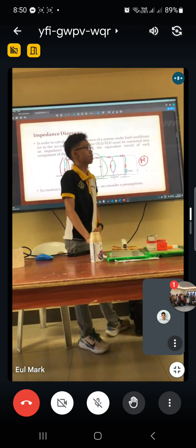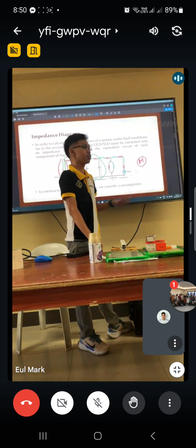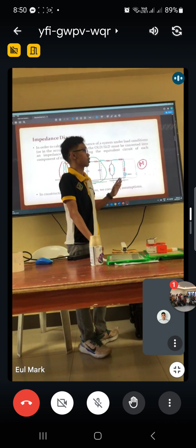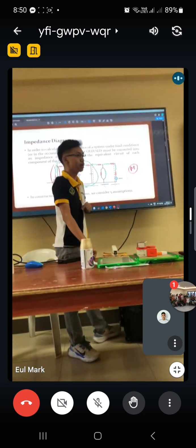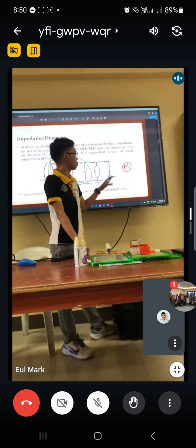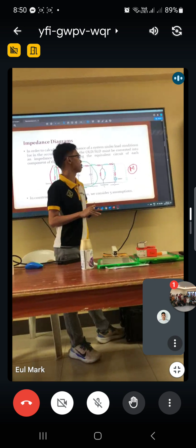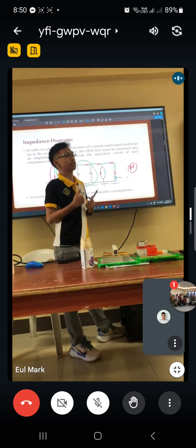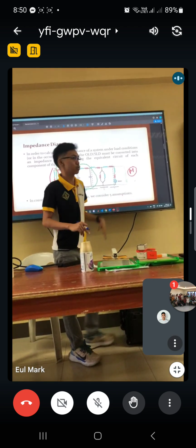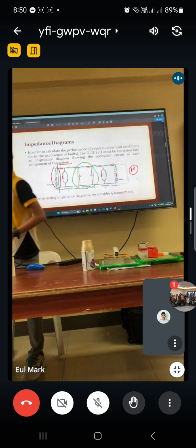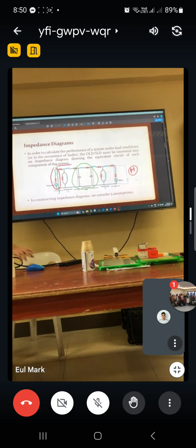Let's say you have a process load, usually motors. Static loads are those without rotating parts. A motor's load depends on what it drives. If you have a heavy load on your motor, the torque is higher, and so is the power. That's why your motor load fluctuates. A static load is constant, let's say 40 plus j60 MVA. So that is how loads are represented.